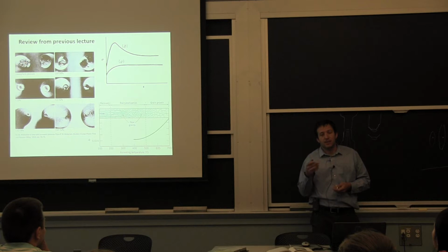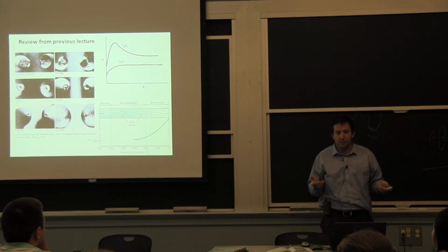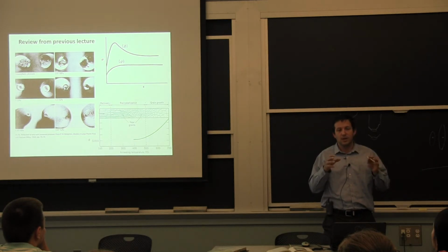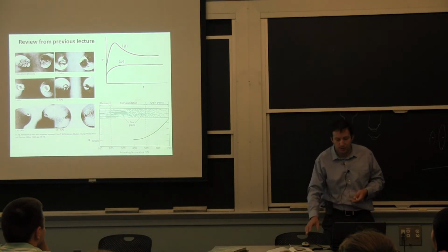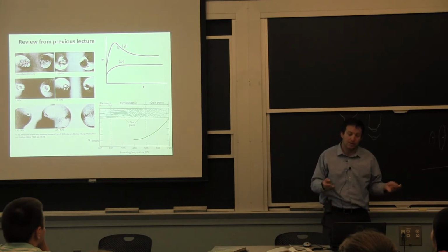The significance of the peak in force is it will make the deformation less homogeneous, and it's a situation where you could have tension in a forging, for example. So you have to keep track of and try to optimize your flow stress. So a material that's going to go through these transitions is something to be careful about, and maybe try to avoid it depending on the situation.